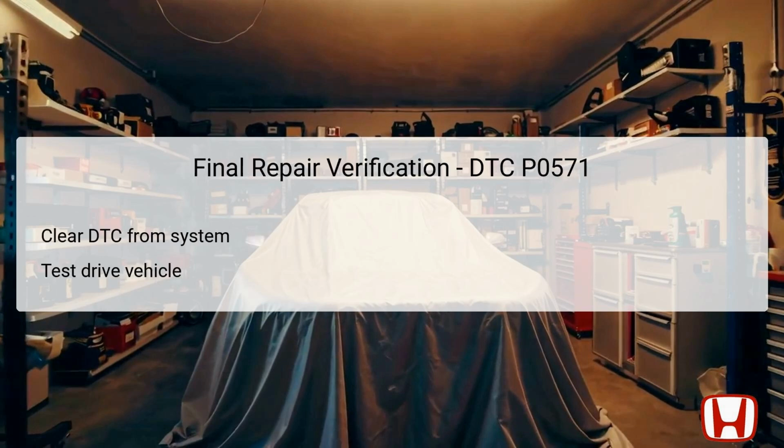After completing all troubleshooting steps for DTC P0571, the final repair verification is crucial to ensure that all issues have been resolved. Begin by clearing any diagnostic trouble codes, DTC, stored in the system utilizing the Honda Diagnostic System HDS.